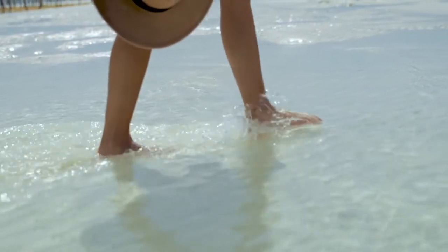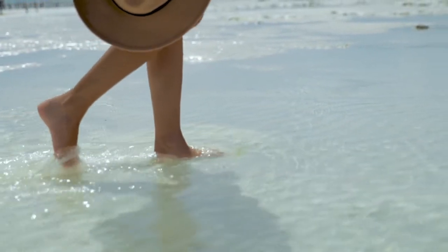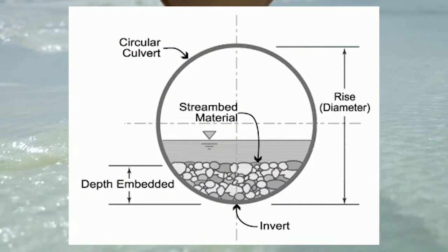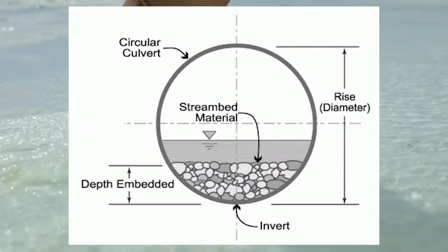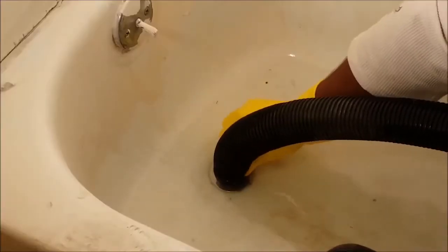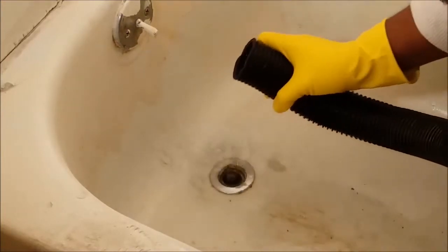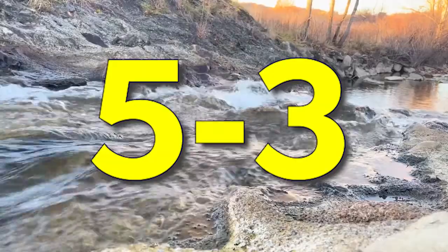2. Water flow inside a larger pipe is relatively shallow. The solid waste does not flow on shallow water but tends to remain at the bottom of the pipe. This is practically the most common cause of the many clogging problems of the drainage installation. 3.